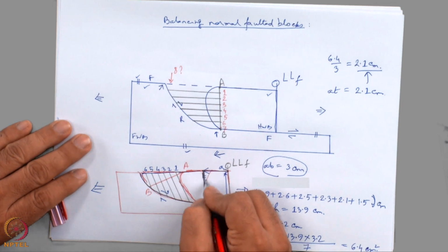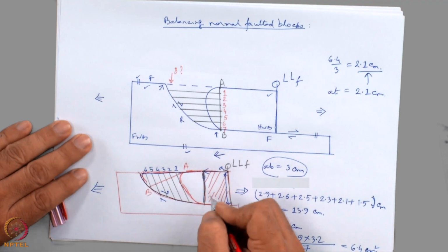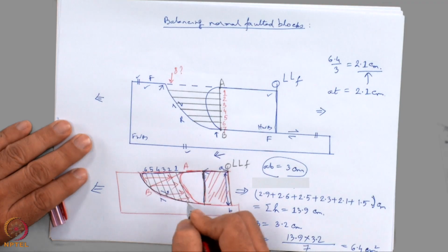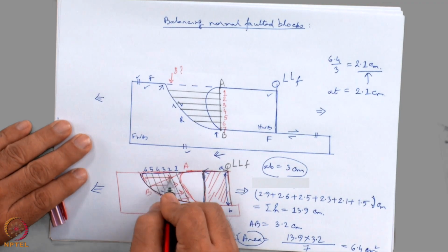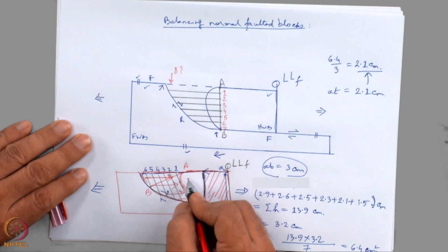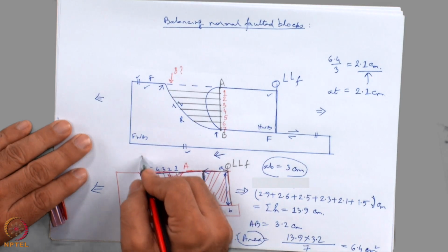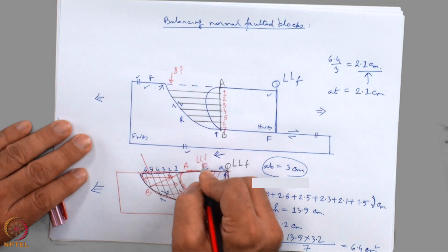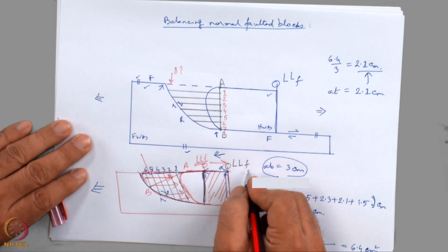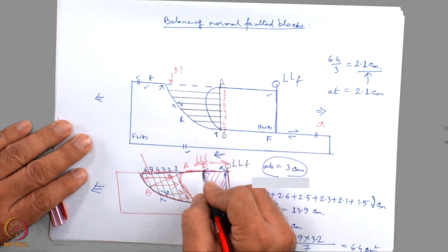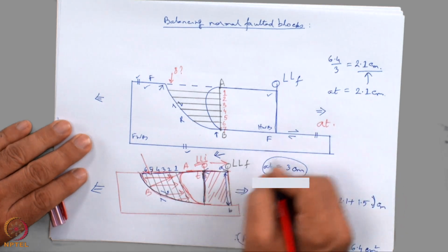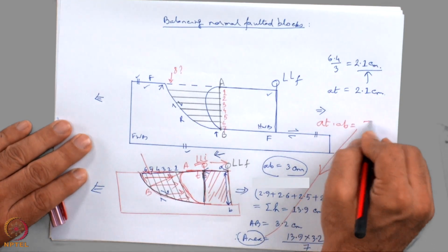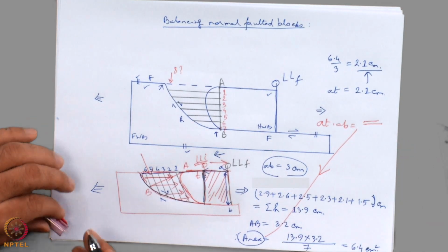So, what has happened here? This is the area gain when this kind of movement took place. This is a schematic presentation that the block has moved, internal deformation of the block also happened. This is the area opened up, result of that the loose line initial moved to the loose line final position. Note that the AT distance multiplied by AB distance is equal to this particular area calculated. In this way, the area balance is maintained.